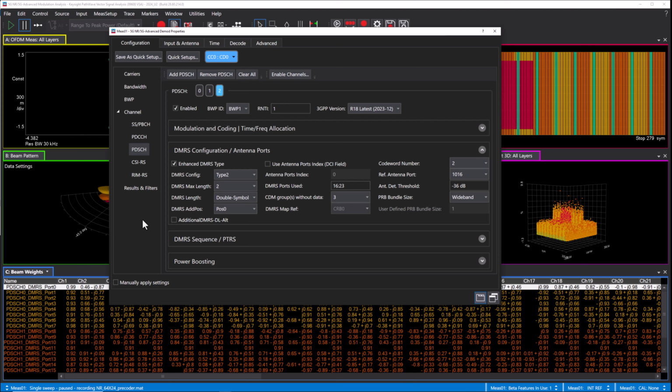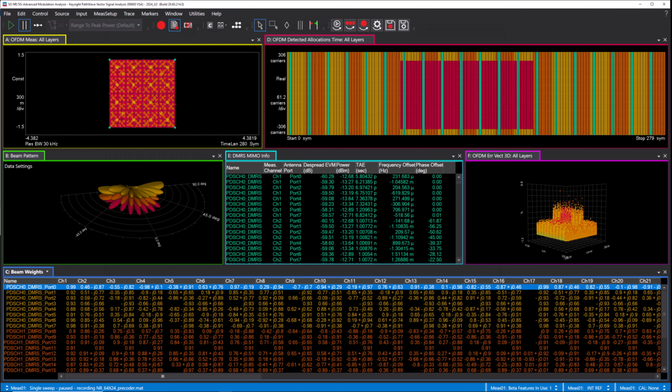The key point here is that the maximum number of antenna ports is expanded to 24 for multi-user transmission purposes, while a single device can transmit or receive up to 8 antenna ports or layers. For this example, each port is mapped to 64 physical antennas for beamforming.